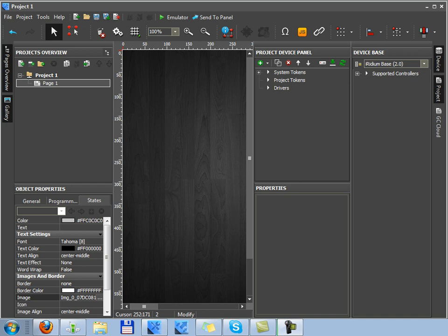This database must include the Global Cache module, which will enable conversion of data from the TCP format for sending through the IR emitter. Data about Global Cache modules are stored in the device base of iRidium GUI editor. If you want to use Global Cache script modules, select the GC database tab. Here you can see all available Global Cache modules. These are iTach and GC100 modules.